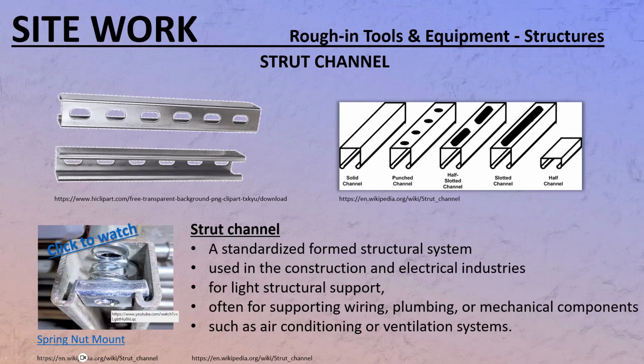So you can use that to mount the strut to the ceiling, or you can use that to mount other threaded rods and other construction to the strut channel. Strut channel is a standardized structural system used in the construction and electrical industries for light structural support, often for supporting wiring, plumbing, or mechanical components such as air conditioning or ventilation systems. You can cut that to length.